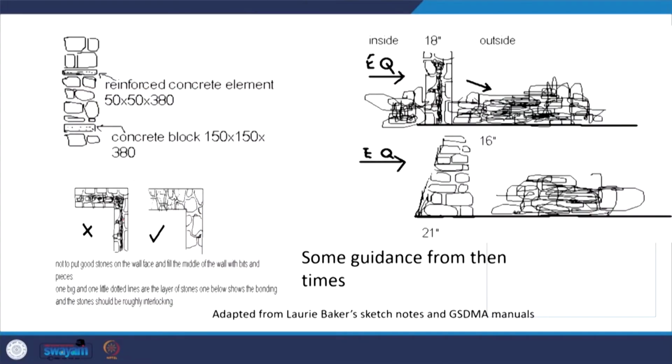One of my initial understandings of stone construction was Laurie Baker's handbook, where he talked about his work in Chamoli, how to construct with stone and how not to construct with stone, the effective ways of bonding, the filling technique, and how we have to taper the surfaces. If you make it straight in earthquake prone areas, it may fall inside the house and affect the people, whereas if you taper it, it will have certain resistance.